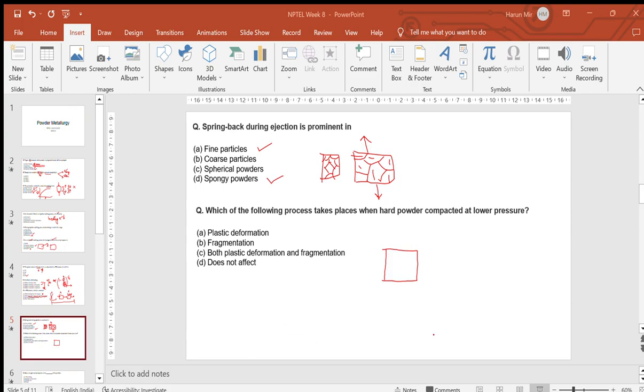And on what basis is this distinguishing? This is based on how we are handling the mold. It is actually based on your elastomer mold. If it is inside the pressurized vessel and you are taking it out of the vessel every time, then it is a wet mold. But if it is present inside the vessel and you are not removing it, it is not a removable mold, but it is present inside the pressurized vessel with some outside membranes just keeping the mold dry, then it is a dry mold. So the distinction is based on your type of mold, and there are two types of molds, one is dry and one is wet.